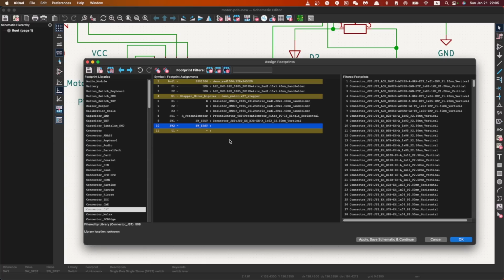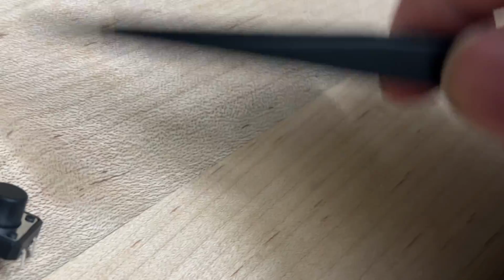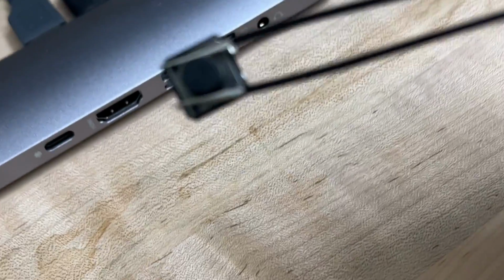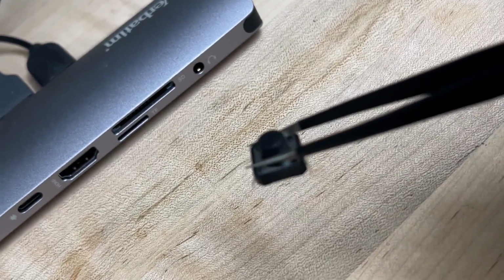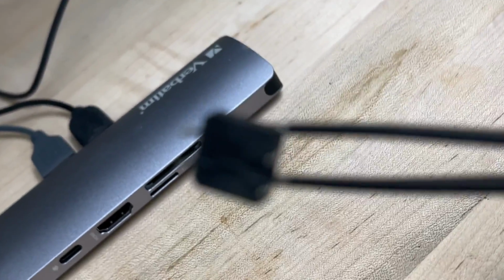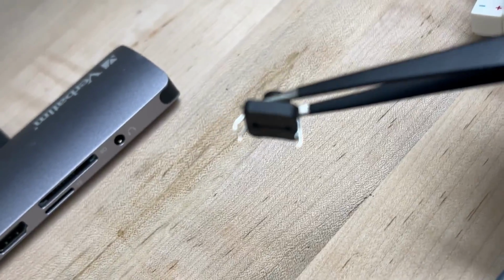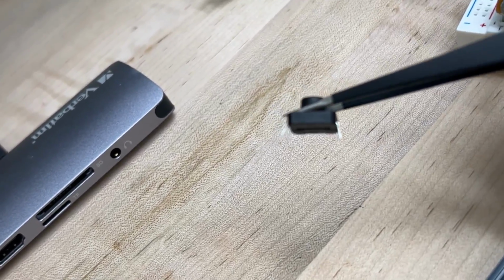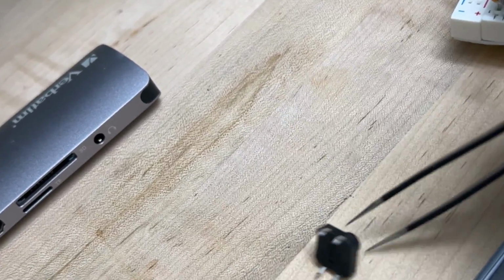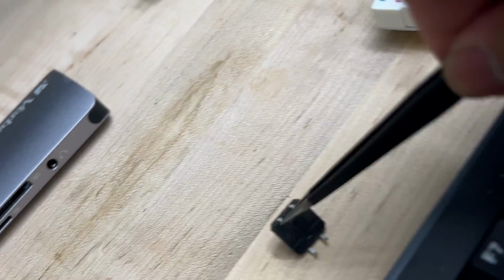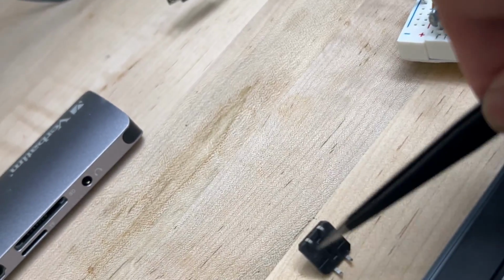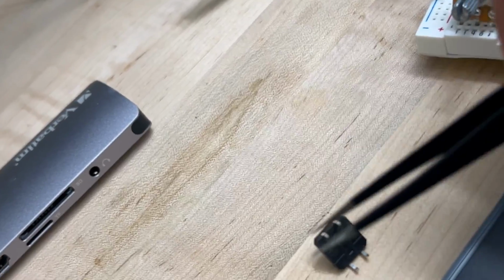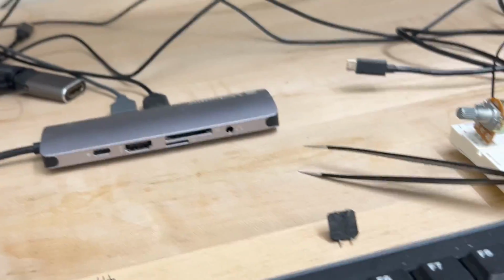Okay, and next for the button, as we can see here, this is a pretty typical button that we can use. You can find this in the makerspace. It has 4 pins in total, but actually there are only 2 pins electronically speaking, because those 2 pins vertically here as the column are internally connected. If you are using a multimeter, let me find one here.